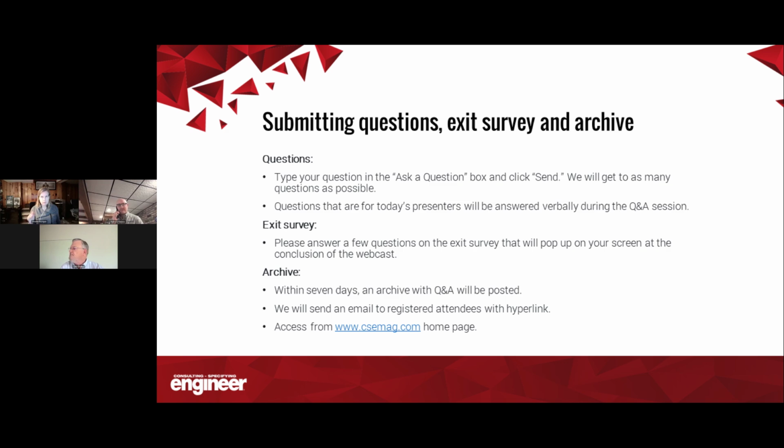Sure. So you both have experience for this next question, so I'm going to pose it to both of you. And Rich, if you could tackle this first. As an AHJ for healthcare facilities, this person sees many level 1 and 2 type 10s for hospitals or some sort of medical facility. During monthly load testing, some facilities cut power by manually shutting the ATS to run the generator at load. This person has suggested this is not the best way to test the system, and you're not allowing the ATS function itself to be tested within the system. Do you agree? Do you disagree? Or what has been your experience here?